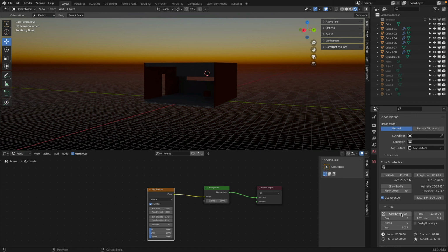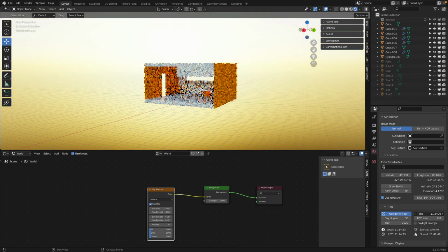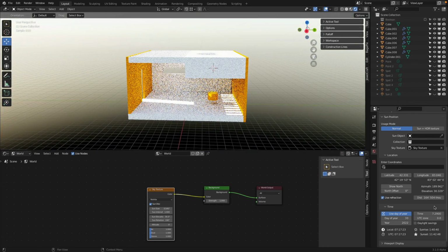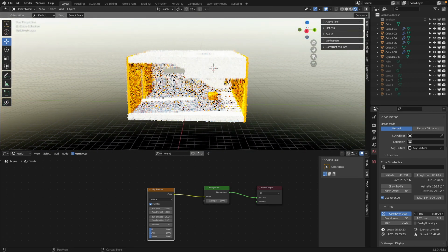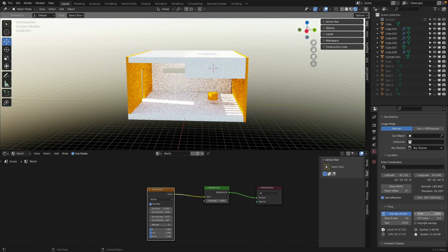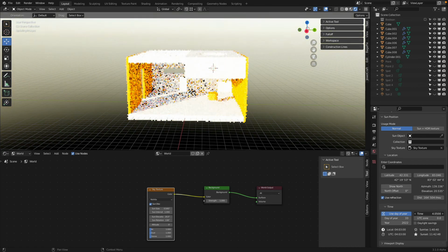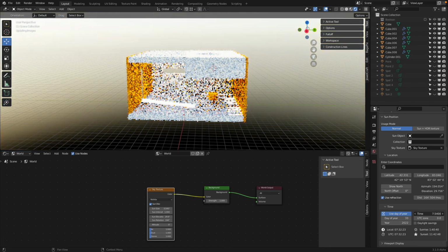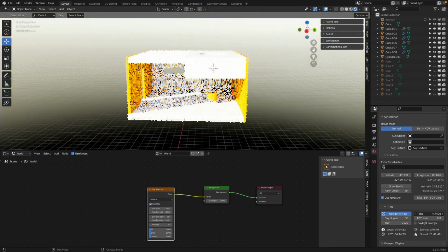And what I can do now is say, hey, use the day of the year and the time, and I can even then at this location see where is sunrise, where is sunset, and study how, when I go through various days or months and the seasons, natural light would hit or illuminate the interior space throughout a day.